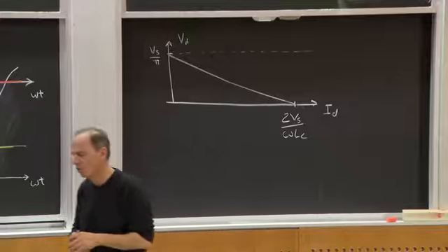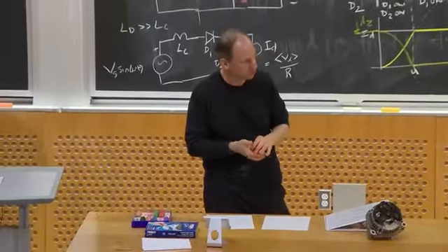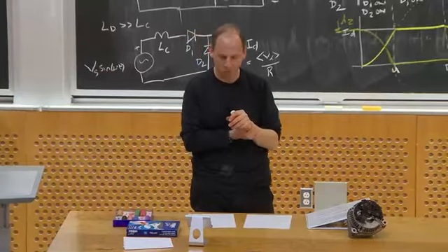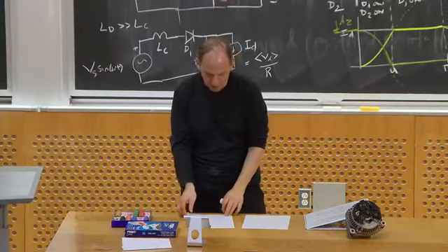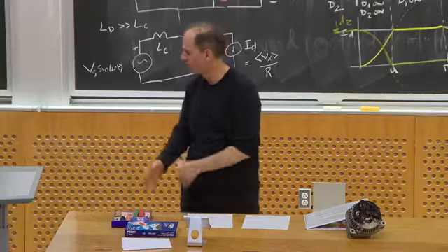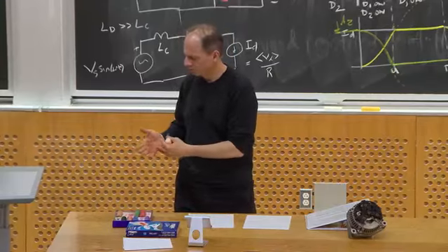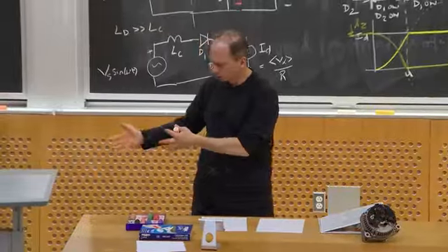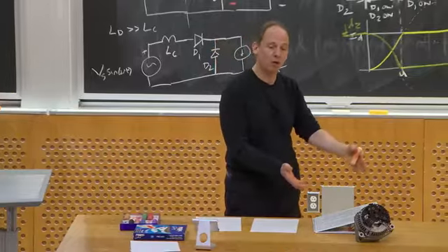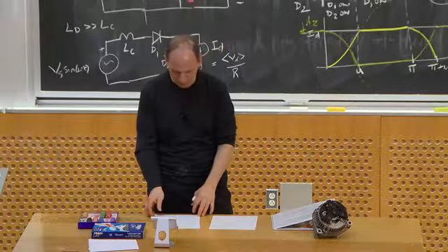Or as we delivered more and more current, the voltage would droop, and then I wasn't getting enough power, so we weren't making our voltage rating anymore. Okay? So this can be a practically important phenomenon, both for line frequency rectifiers, where you're trying to get power out of the wall, or for even a high frequency, megahertz power converter.